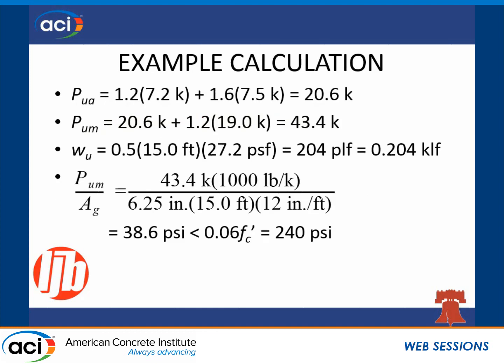We go about calculating our applied factored loads to the panel. Now, those are separated out into 2 different categories here. We have the applied load from the joists on the roof, and then to that we've added the contribution of the mid-height section of concrete of the panel itself, because that does contribute to your P delta effect.